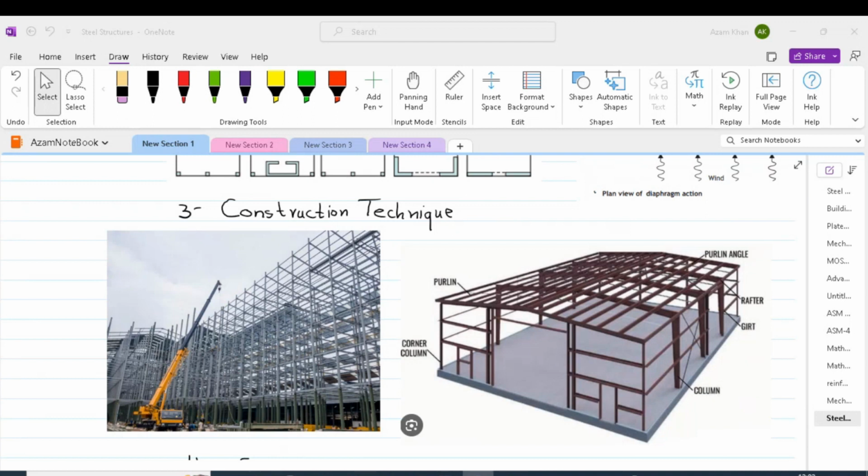In bottom-up construction, the building is constructed from the foundation upward. This is a traditional approach involving the same sequence we have discussed: preparation of site, preparation of foundation, then steel frame erection, floor and roof installation, interior and exterior finishes, then mechanical and electrical systems, and finally the cladding system wrapped around the structure.